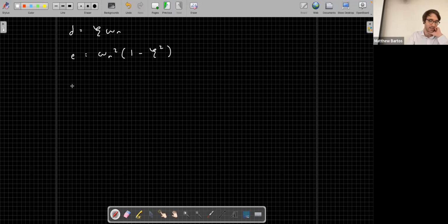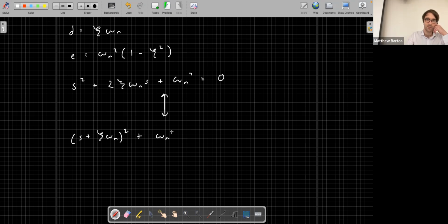Okay, and so we have that our initial expression for the characteristic polynomial, s squared plus 2 zeta omega n s plus omega n squared is equal to 0, corresponds to s plus zeta times the natural frequency all squared plus omega n squared times 1 minus zeta squared is equal to 0.